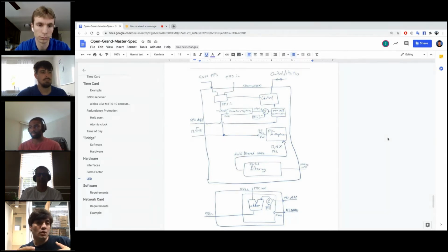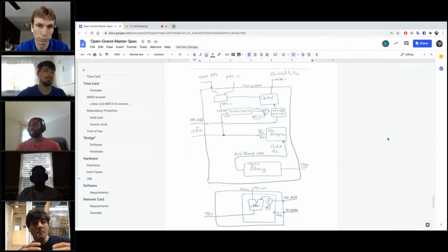Once your GNSS or GPS is gone, you can rely on the atomic clock that you already disciplined in the presence of the GPS, and you can continue on. You can provide all sorts of control schemes, more aggressive or softer, depending on the application. If an application needs more reliability, just add another PPS input or another GNSS receiver, and now you have redundancy. You can also add a second atomic clock for redundancy on that side.